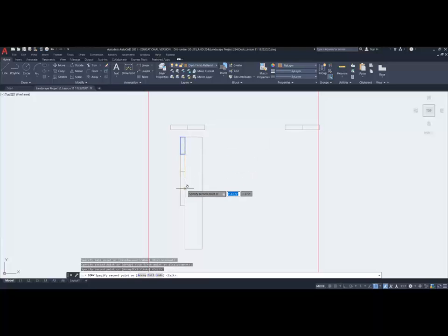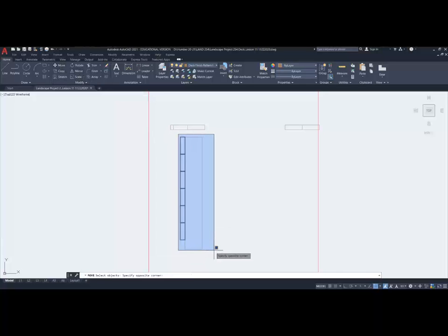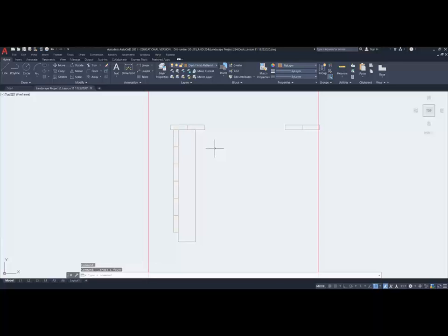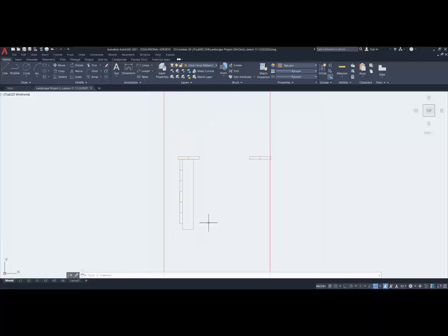along this. Now, none of this is structural in the sense of it's supporting the deck. But what it's doing is providing some sort of support to make sure that the soil that I have in here doesn't go outwards. So I've got to decide where I want this relative to that position. I want to have a 1-inch lip, so I'm going to select 1. I'm going to offset the existing information inwards and then move my planter framing to that location. Remove my reference line, and this will be the outside of my planter, and this will sit on the actual deck.